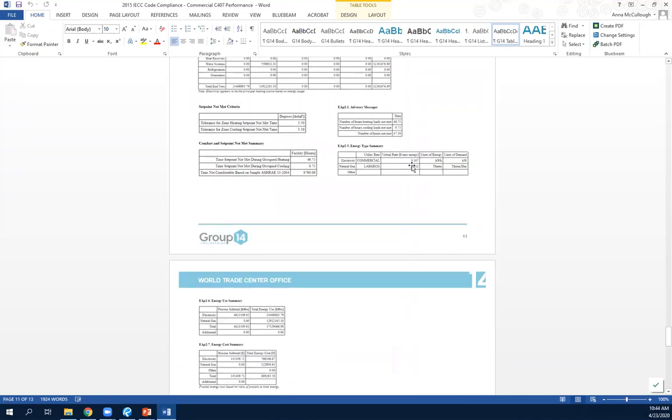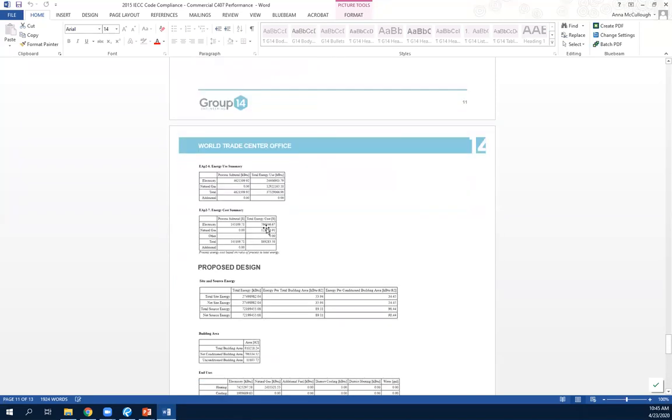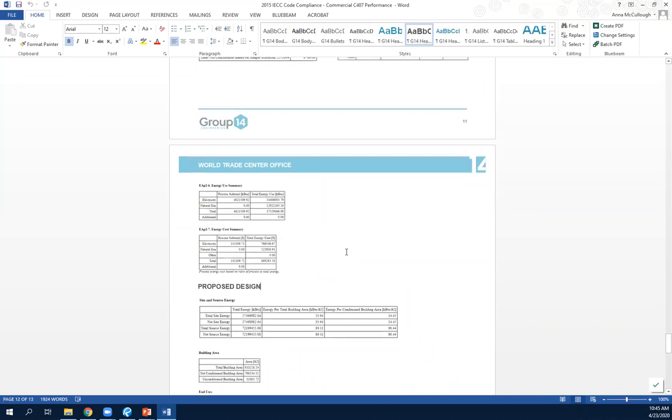And we have located here the virtual rate, dollars per unit energy that's listed here, unmet hours, and then there's also total energy costs. And this is what you want to be reviewing to make sure that what they have listed above to show percent savings matches what's coming out of the energy model. Right on. So for the folks on the webinar, if you just Googled OpenStudio energy modeling software, it would just come right up. Yep, absolutely. So there's no reason for me to send a link or anything.